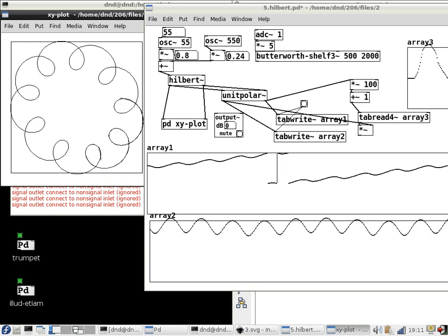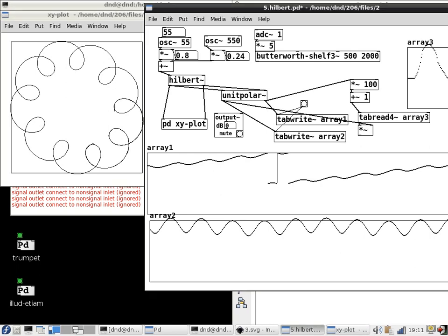So I'm not sure. Actually, it turns out that this particular phase relationship isn't so bad because if you figure it out, this is FM, and FM makes sinusoidal sidebands. This is AM, and AM makes cosine sidebands. And these sine sidebands are actually out of phase with the cosine sidebands and are phased in exactly the right way to make the actual resulting sidebands be in phase. But that would be pages of math for me to show you that. Or it would be one simple observation, which is this.